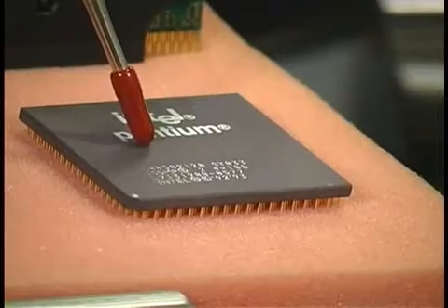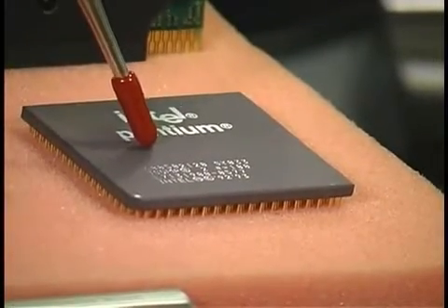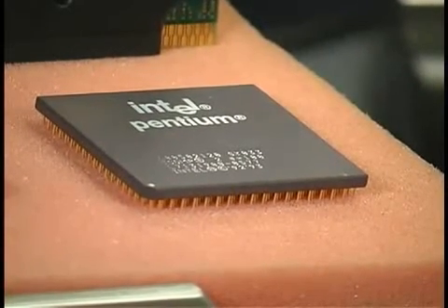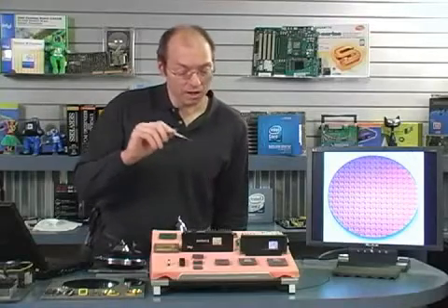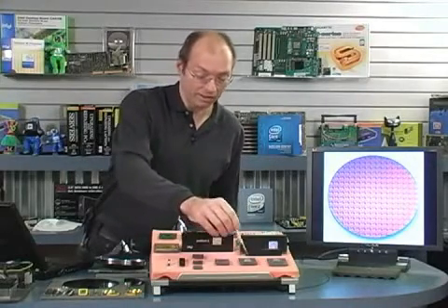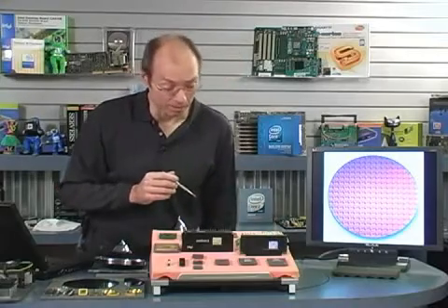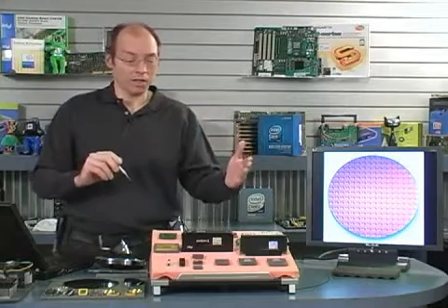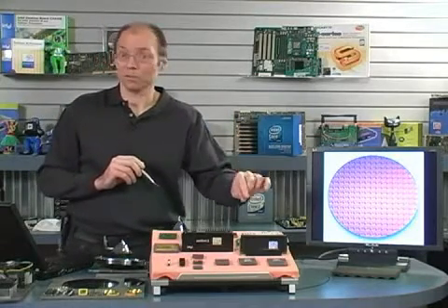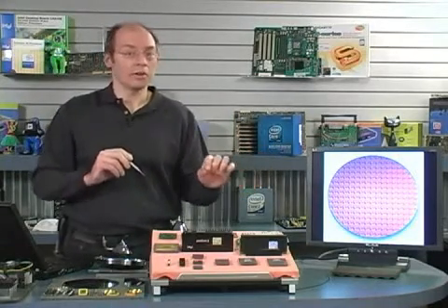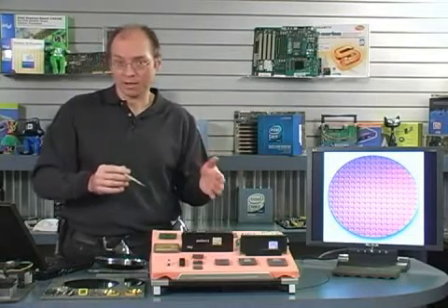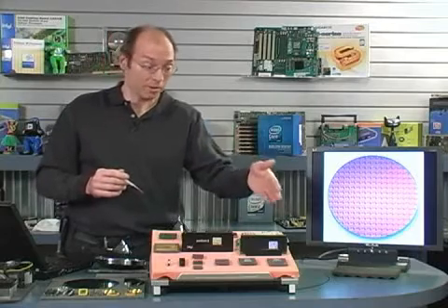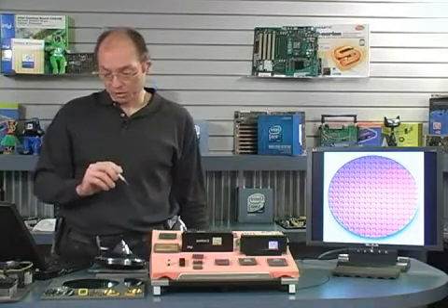Then we have here the 586 processor, which really wasn't called a 586, it was called a Pentium. The first Pentium came out in 1993 and had just over 3 million transistors on it. The Pentium was also, like the 386 and 486 before it, a 32-bit processor. Now, that concept of cache I was telling you about, yes, the Pentium also had the cache built into it, but this was what we call level 1 cache. During those times, level 2 cache was still found on the motherboard, and therefore it ran at slower motherboard level speeds instead of faster processor level speeds. So the next processor would change this radically.